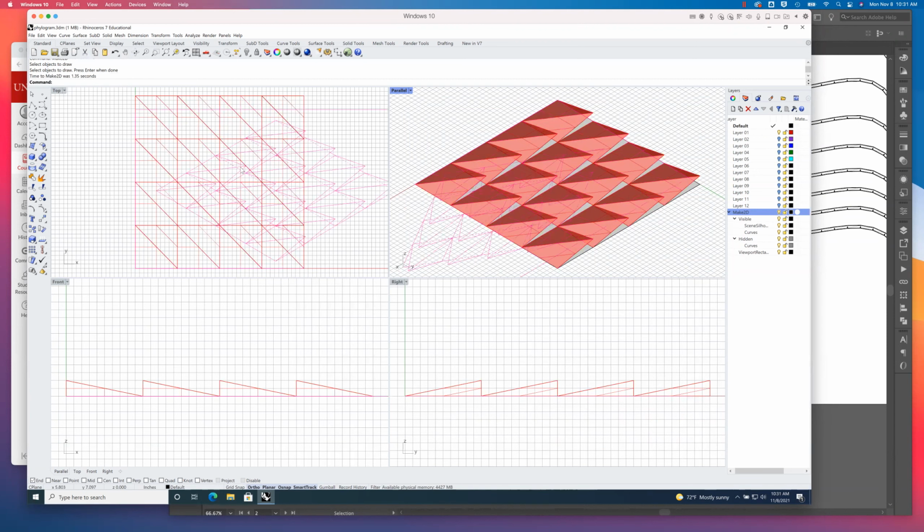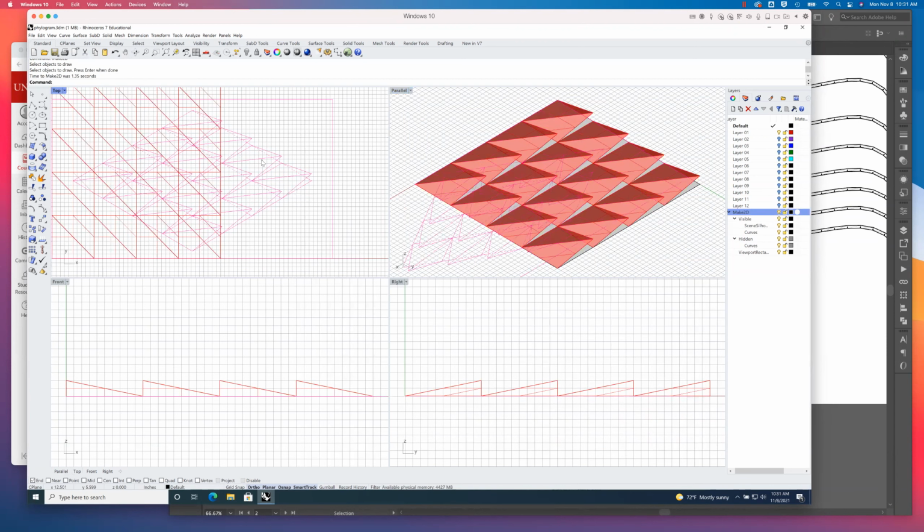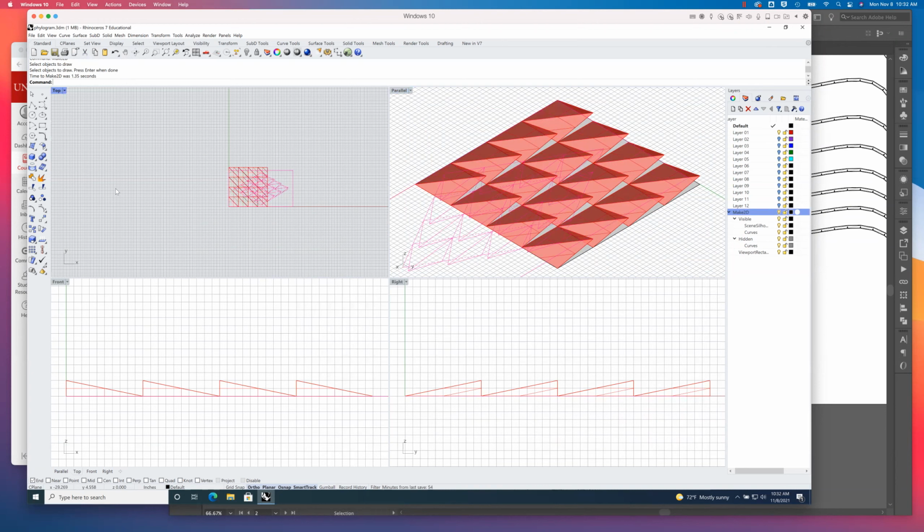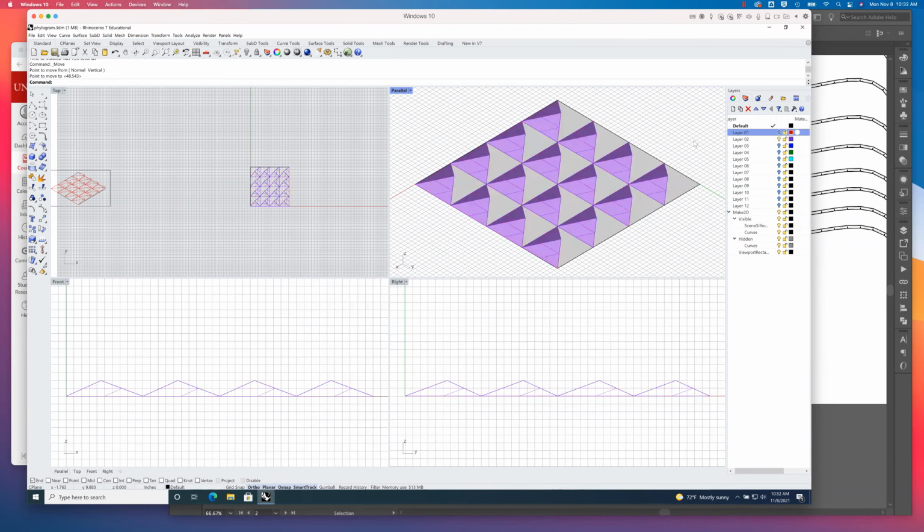All right. Now you can see once it's done, it's giving me that flattened axon drawing of this system on the XY plane. I can see it as an axon drawn on the XY plane in top view. I can move that out of the way. All right. Now I'm going to go back to parallel. I want to make sure I do not move this viewport around. Keep the same size, keep the same shape, and don't accidentally rotate the view or anything like that. And I'm going to turn on layer 2, turn off layer 1. It's time to do another make 2D.